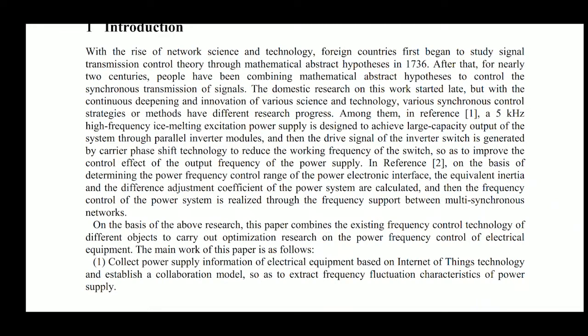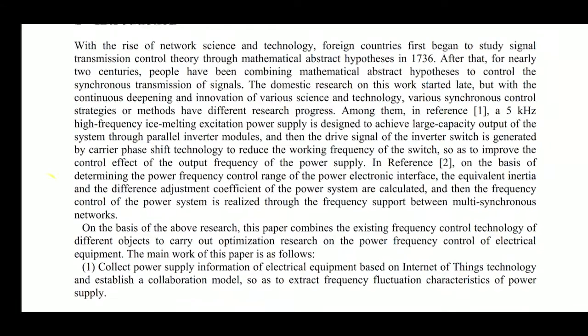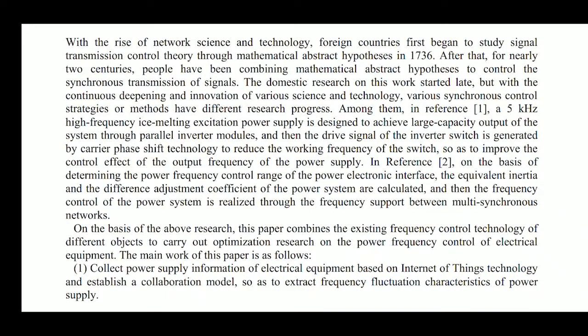Among them, in reference 1, a high-frequency ice melting excitation power supply was designed to achieve large capacity output of the system through parallel inverter models, and then the drive signal of the inverter switch is generated by carrier phase shift technology to reduce the working frequency of the switch, so as to improve the control effect of the output frequency of the power supply.